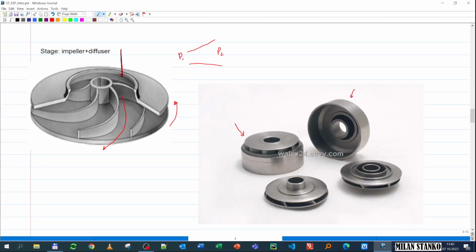So the way it is stacked together, and this is the diffuser here, and this is also the diffuser. You see here the diffuser, the fluid goes from here, enters, so it will be 1, enters through here, this will be 2, then comes out through here, this will be 3, which is the same 3 that we have here and the same 2 that we have here. And then after that, it goes through here again, this will be 4. It goes inside the diffuser and then exits through 1. Okay, so then it repeats again.